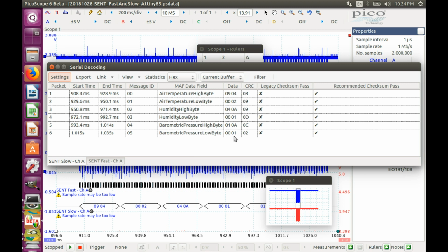and for this chip, to get the temperature in Celsius, you have to subtract a value that is approximately 260. So this means that the temperature of the chip at the time of the measurement was 22 Celsius, which is pretty much what was in the room.